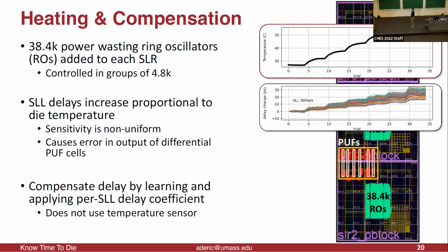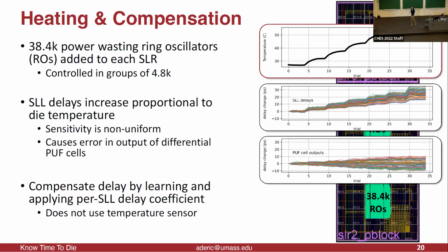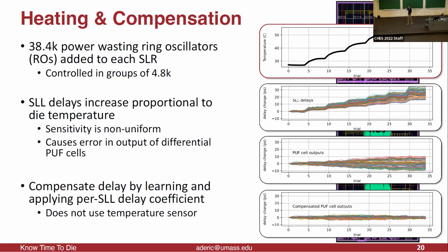This for us is bad because we're using differential delays, so they're going to drift all over the place. Fortunately, for each of those, you can calculate a compensation factor and then apply it. Once you do that, they're stable again.